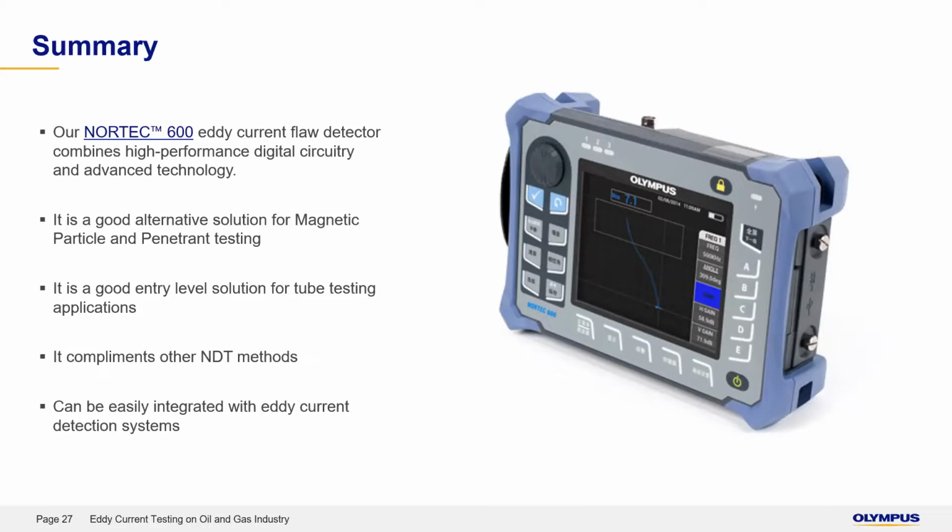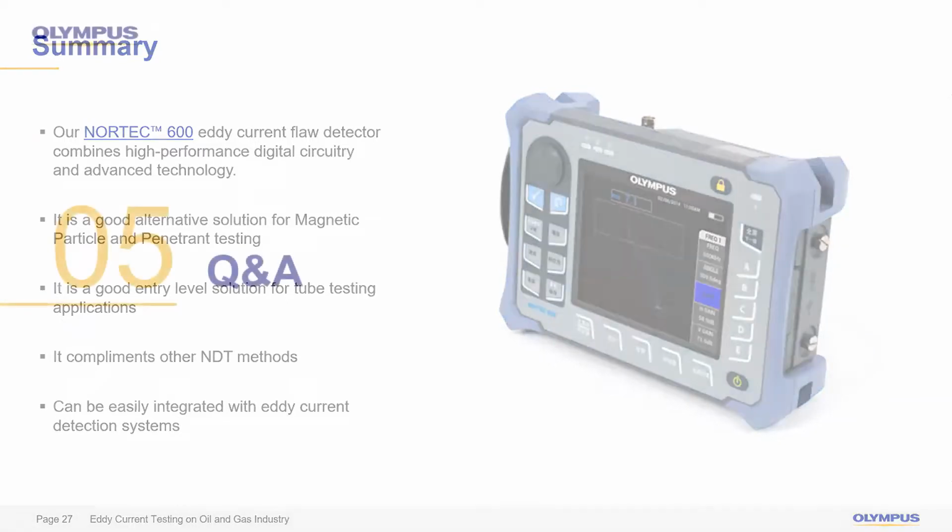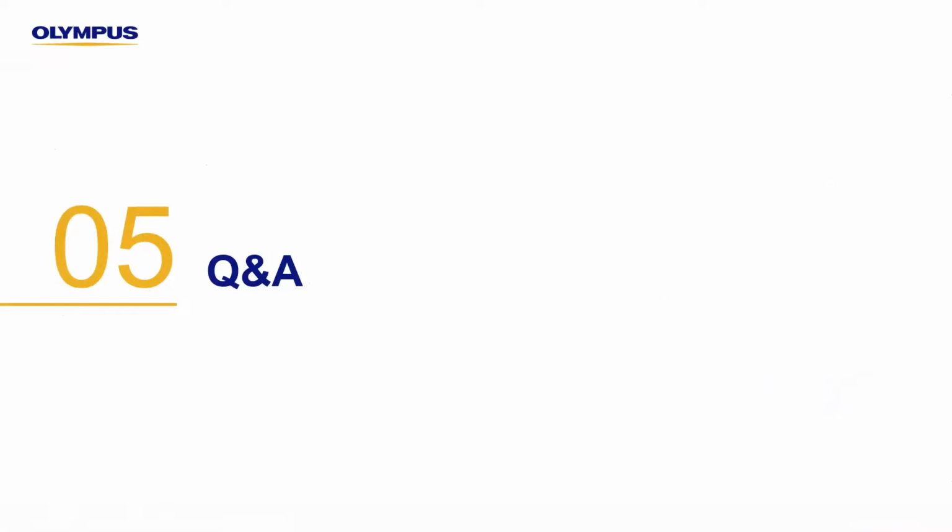So before we wrap up, we would like to share a few answers to some of the questions we received during this webinar. Let me just pick a few out because of time. The first question is, can you scan parts with any type of coating using eddy current? It can, but only non-metallic coatings like paint. Metallic coatings will give false readings due to their conductivity properties.